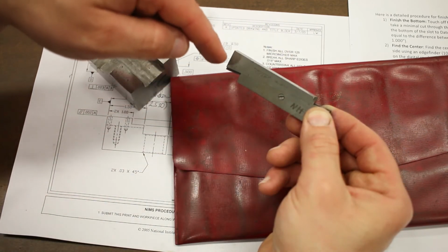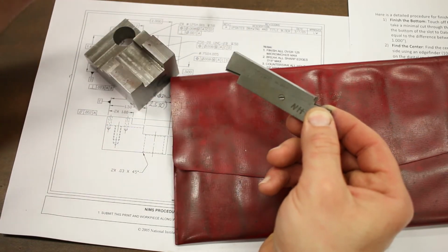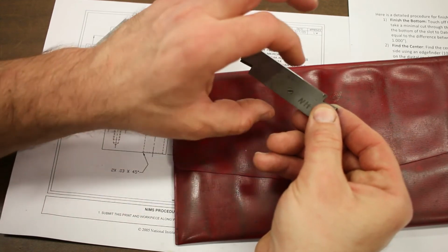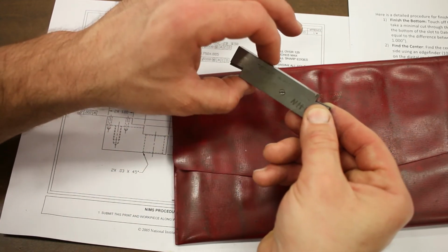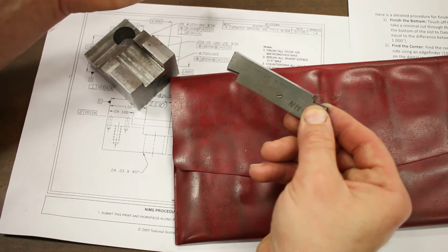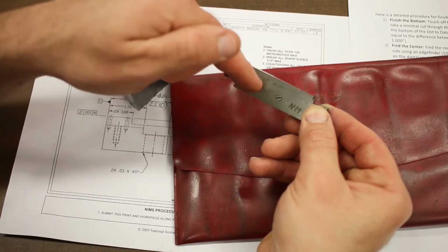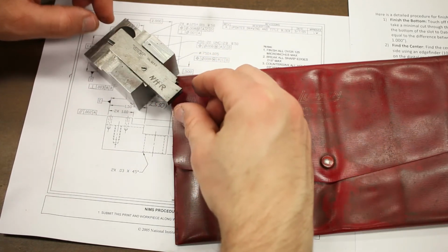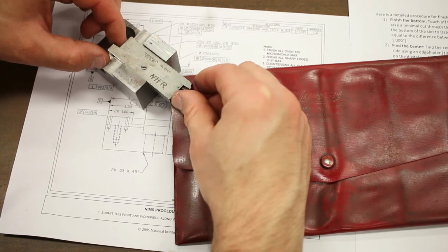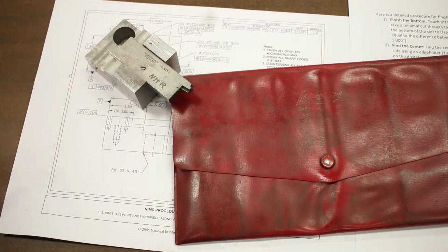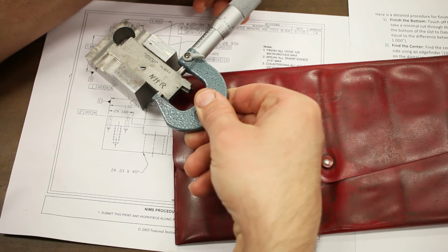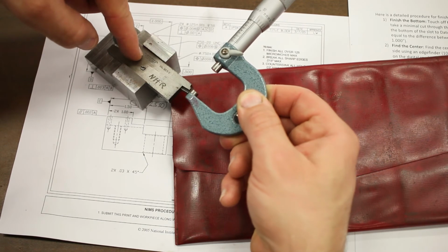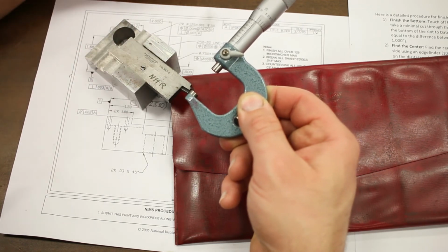This is useful for a number of reasons. As the name adjustable parallel suggests, you can set these to whatever size you want, lock them, and then you've just made some kind of a setting gauge or a parallel of an exact size that you want. But these are also a really good way to measure the inside of slots. All we have to do is install the adjustable parallel, open it up so that it conforms to the inside of the slot, and then we can measure over that directly with a micrometer. So you should really think of these as the equivalent of telescoping gauges, but for measuring slots rather than holes.